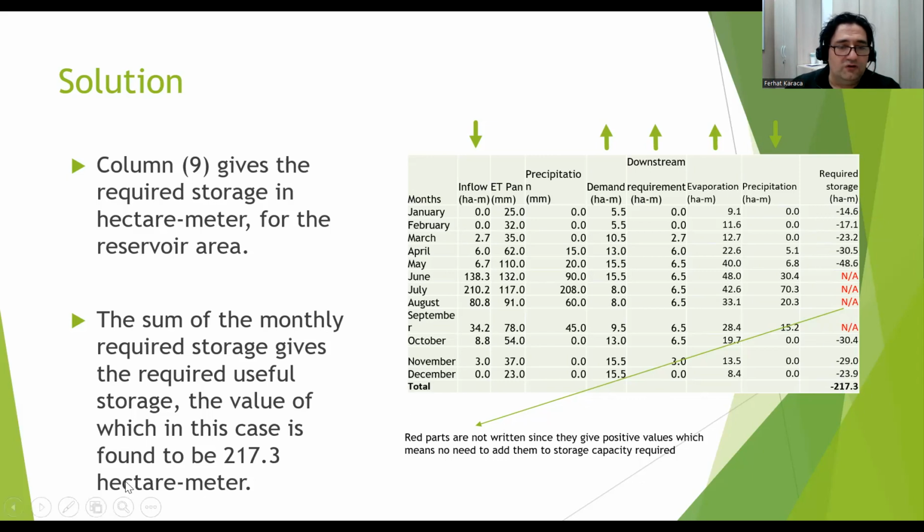So if you are going to have, for example, a 20 hectare water holding area, as a kind of dam, then you can easily calculate what should be the depth or height of the reservoir by using this value. So this is a typical capacity unit, and you are going to use this capacity to calculate the reservoir height and other things. This is an essential calculation in water engineering for reservoir or dam calculations.